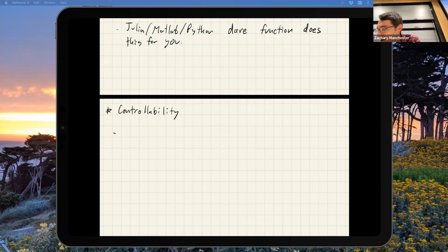All right. So the basic question here is, how do we know if LQR will work on a given system? This is actually surprisingly subtle. Remember we said on nonlinear problems, you basically always linearize, as in Newton's method, and you get an LQR problem. So one of the tricky things is if you're solving a nonlinear problem iteratively with Newton's method, it's actually very easy to end up with subproblems that aren't controllable when you're linearizing.